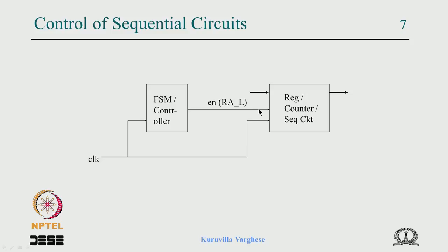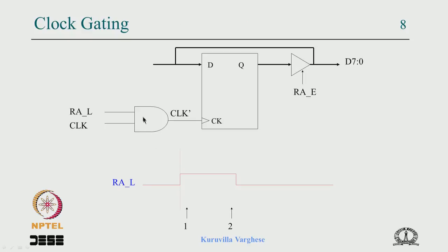So when the latch is high and the clock comes, the data gets latched, and a possible implementation was this, and we found the problem with it, that two kinds of active edges come here. The first one may not meet the timing requirement for the data. The second one could create a timing problem, and if this is used, I said, to clock a counter, it might count twice and so on.